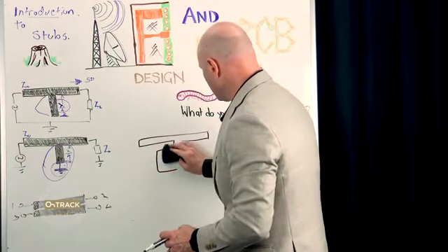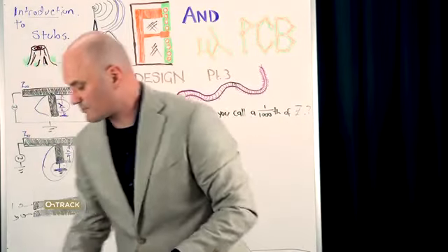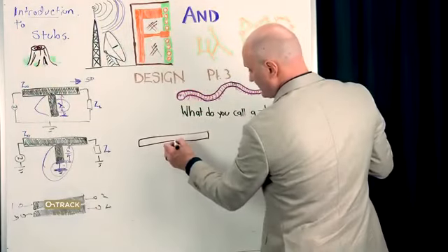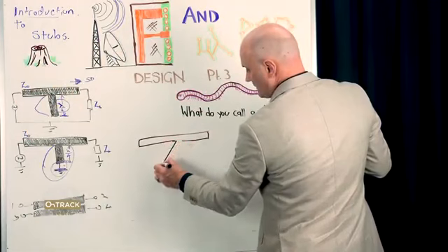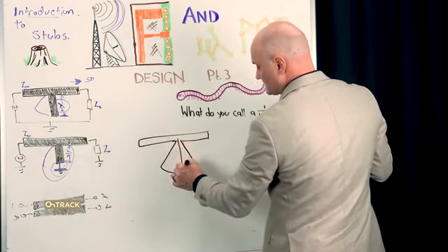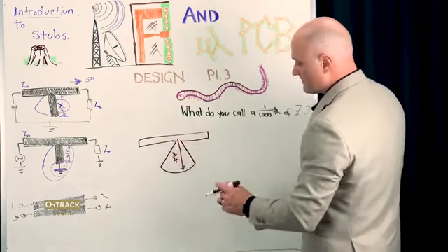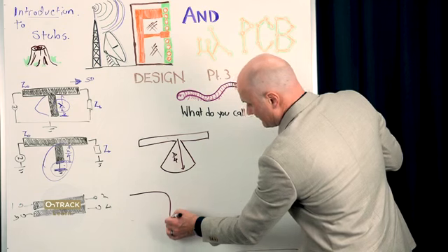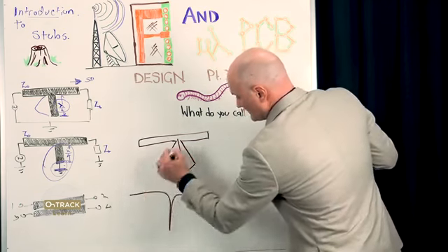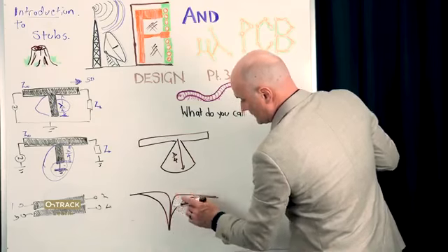A similar approach that's a bit more common, and you would have seen this probably if you've ever looked at an RF board, is to put a radial stub. And this still has a radius of typically a wavelength on 4. It may be less, but this is used to broaden the bandwidth. So instead of having a very narrow notch, doing this one, we have a broader notch like this kind of shape.